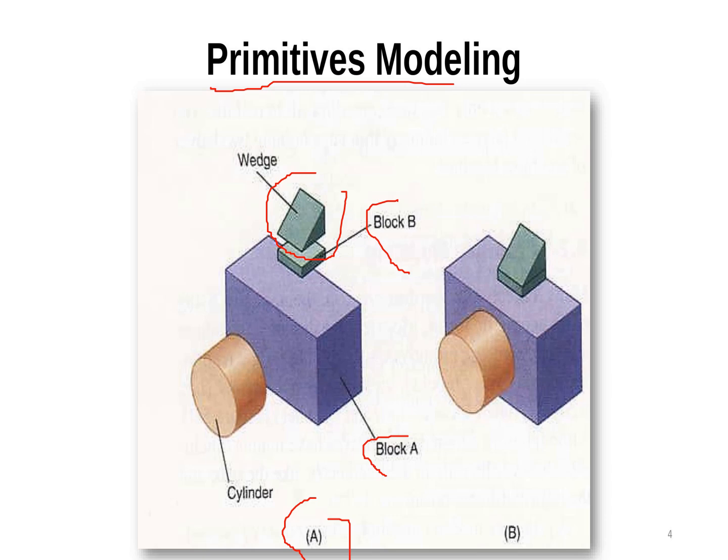All right, so the key concept here is that this method is widely used in early stages of computer-aided design modeling because it is fast and intuitive, makes it suitable for conceptual or mechanical part. So this is often used in constructive solid geometry, CSG, as part of the Boolean operation, which consists of a union, subtract, and intersection.